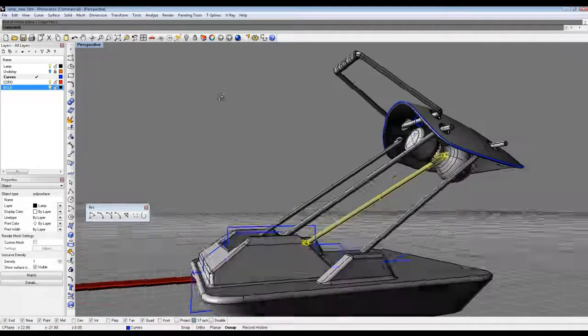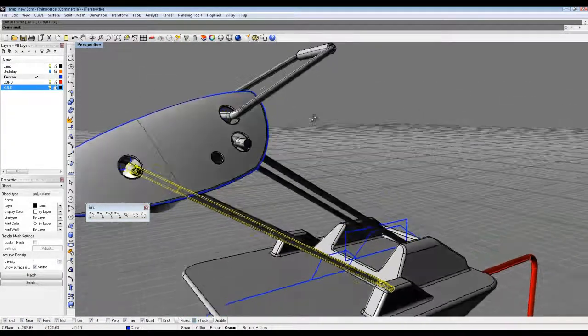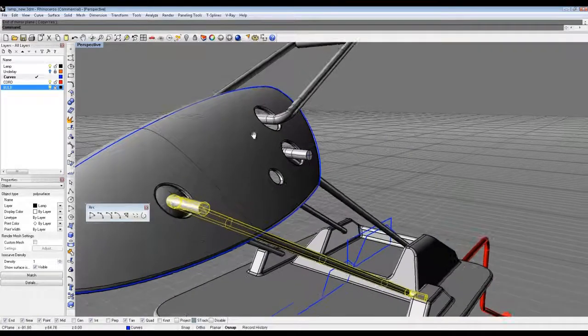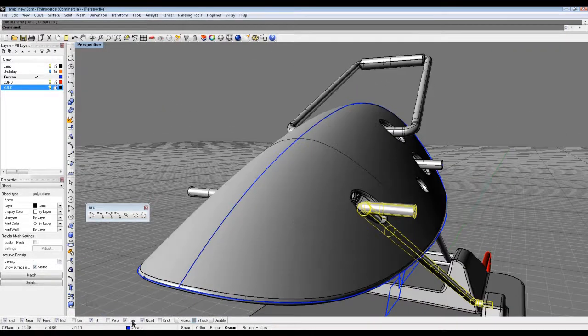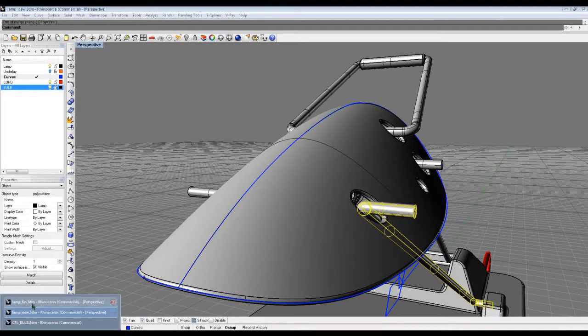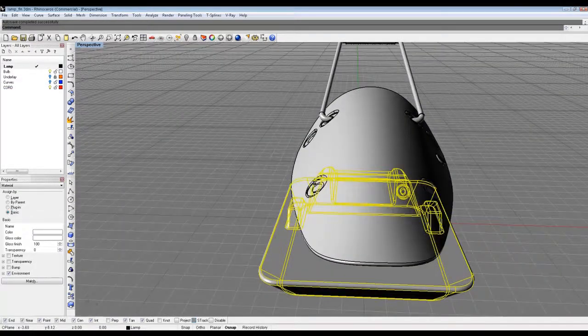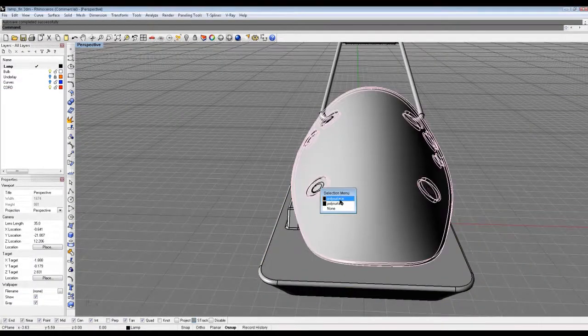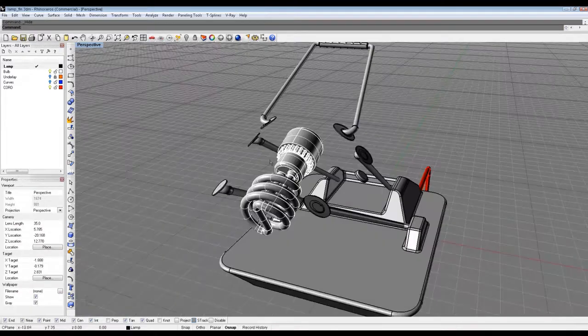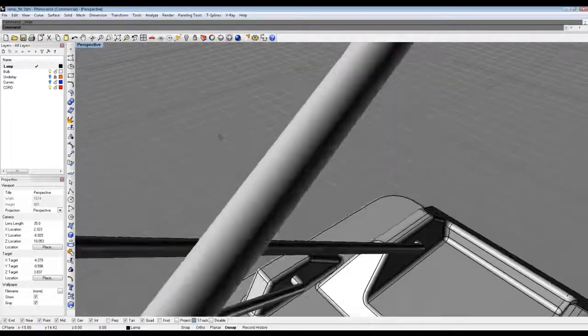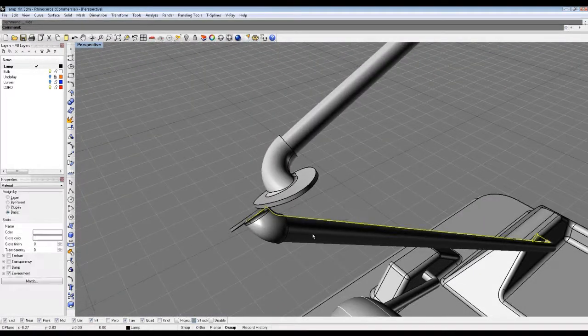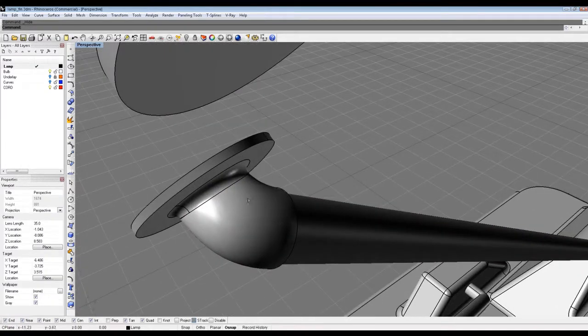Now, if you wanted to detail this, one thing you can do is actually add some plugs in here. If you remember from the final version here, I have these like, let me hide the lampshade for a second. I've got these plugs that are in here. Now, what I did for that was I actually took my original curve and exploded it. So just the radius was what I was grabbing, and did a pipe with a larger diameter.